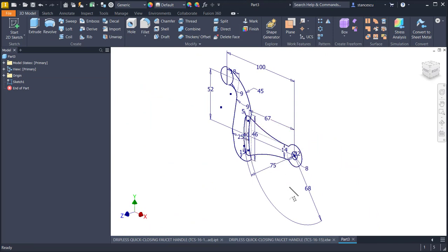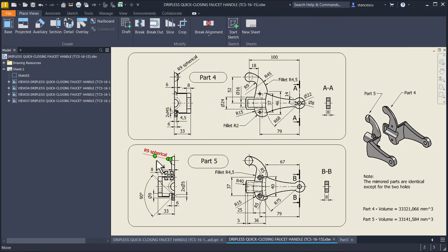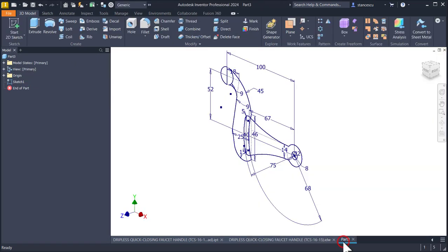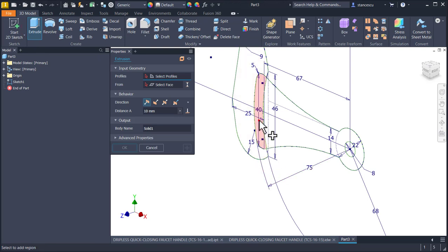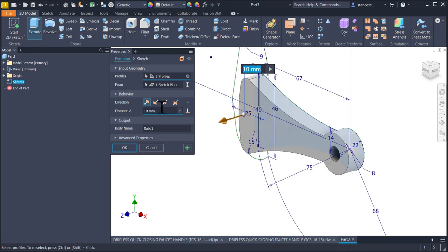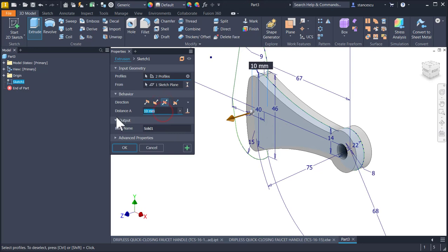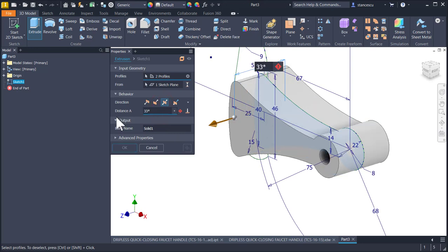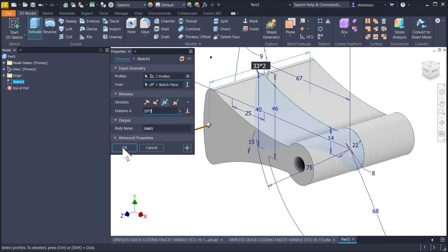this contour and I take care of the dimension, which is 33 plus 33, because I create the volume containing both halves. Extrude this and this symmetrical on 33 multiplied by 2. Okay,